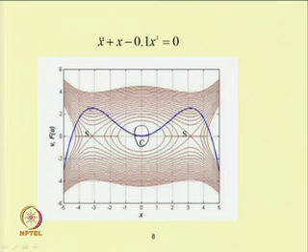So, this shows the potential. This is the variation of the potential energy, and these other curves show the flow of the response. So, one can perform the qualitative analysis to find the different types of response of the system. These responses, written S, C and S, the saddle point and the center, are the fixed point responses of the system. One can obtain the fixed point response of the system by putting the time varying terms to be 0.